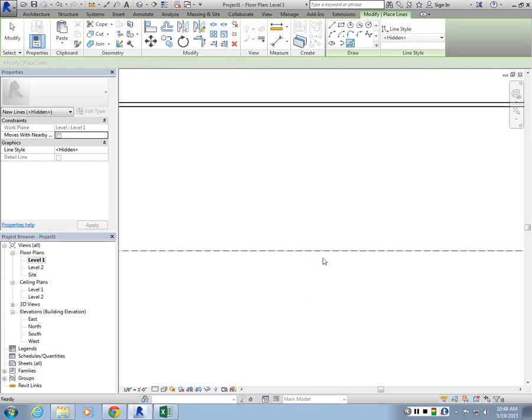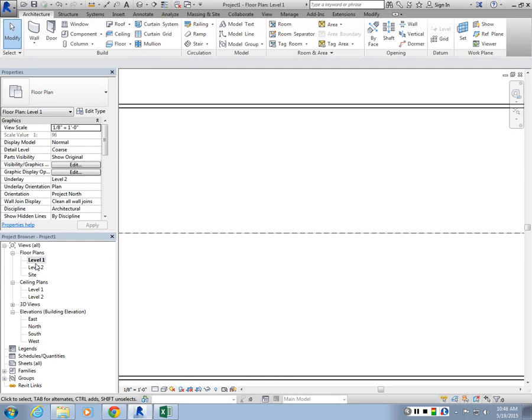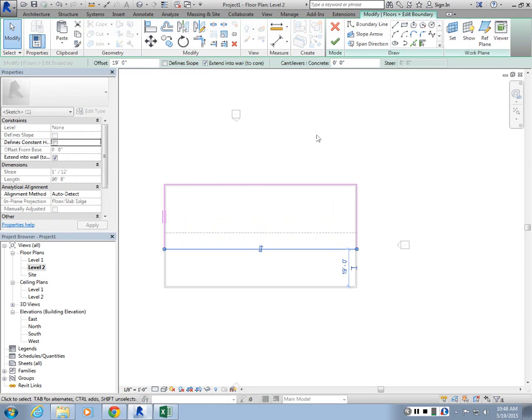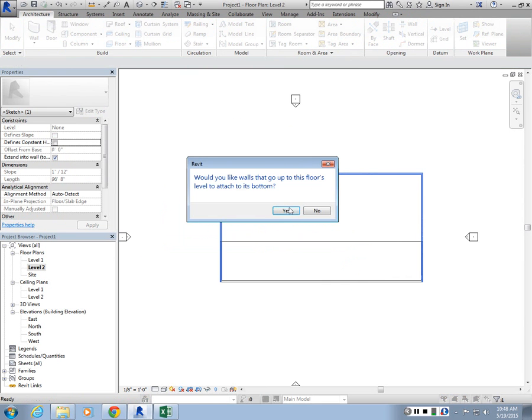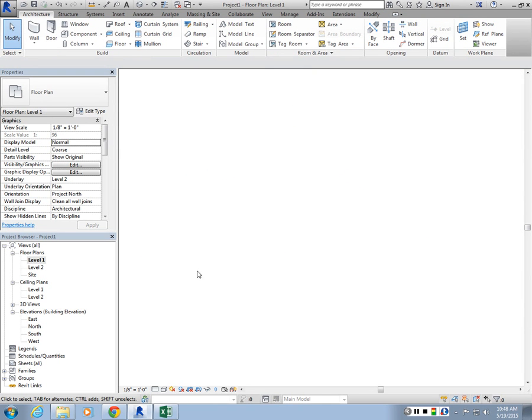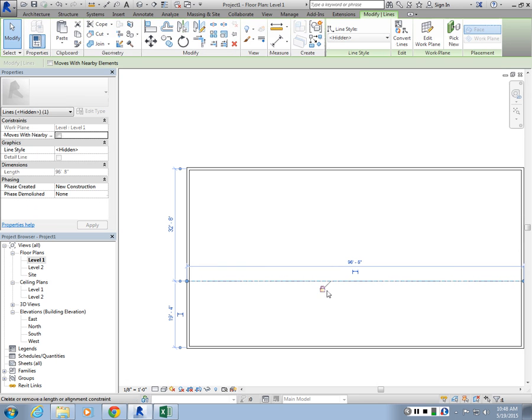And what it does is basically it adds a dashed line there representing the overhanging floor, right? And then if I move it, I'm going to hit yes, unjoin. If I move it, the dashed line will move with it because I established also a constraint when I created it, right? I locked that relationship. So it's following the floor slab above our head now.